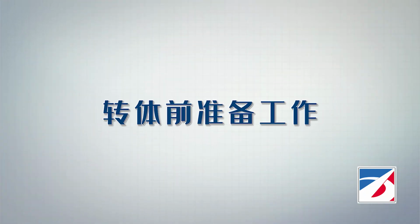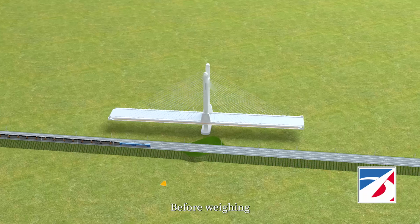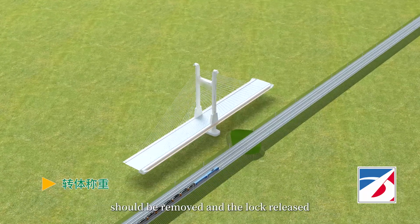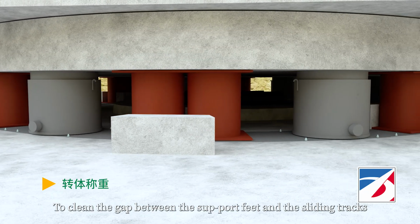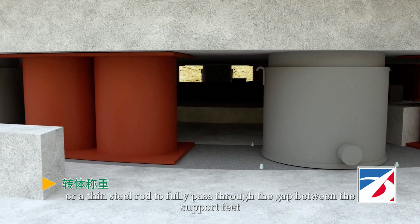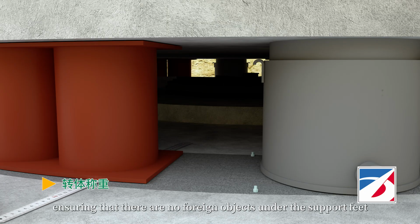Preparations before swivel. Procedure 1. Weighing. Before weighing, the swivel bridge support or hanging basket equipment should be removed and the lock released. To clean the gap between the support feet and the sliding tracks, make sure to use a steel ruler or a thin steel rod to fully pass through the gap between the support feet and the sliding tracks, ensuring that there are no foreign objects under the support feet.